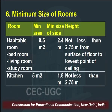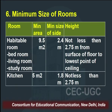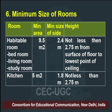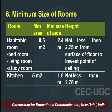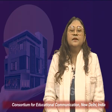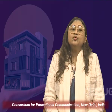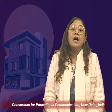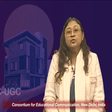Minimum room sizes are also given in all of the building bylaws. Starting with the habitable room, meaning where a person has to stay: one side of the room will not be less than 2.5 meter and the minimum area of the room will not be less than 9.5 square meter. In this way, all the values of the various rooms that you are going to use in your design are given as per the bylaws, and these values have to be followed in depth and to the very last value of the bylaws.